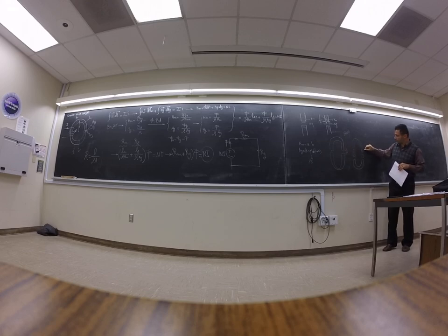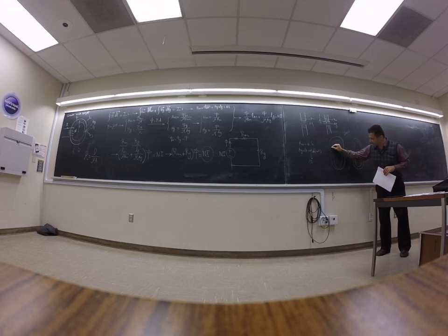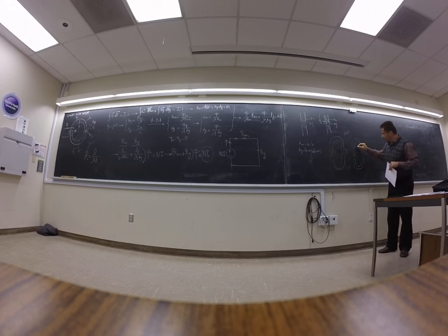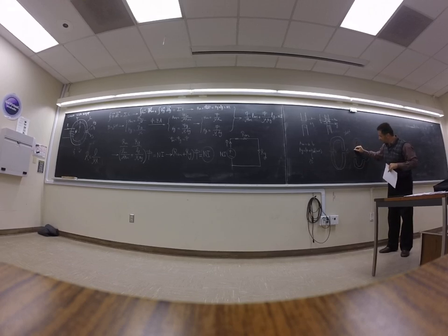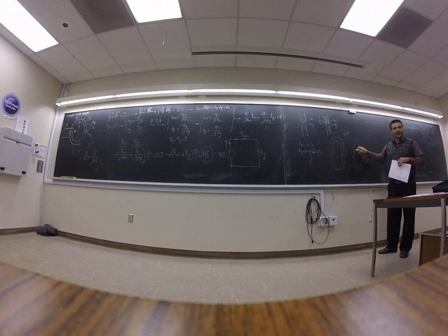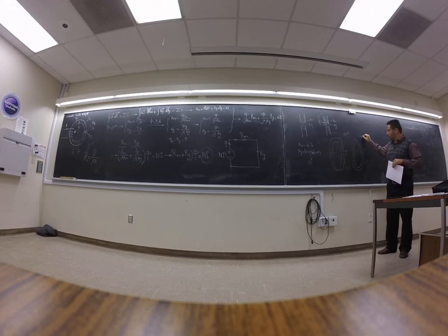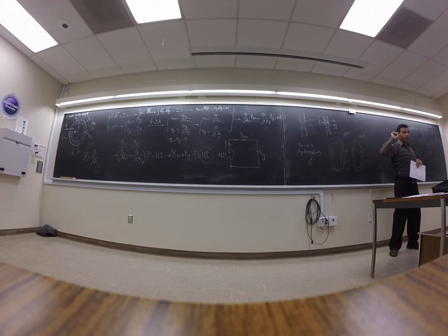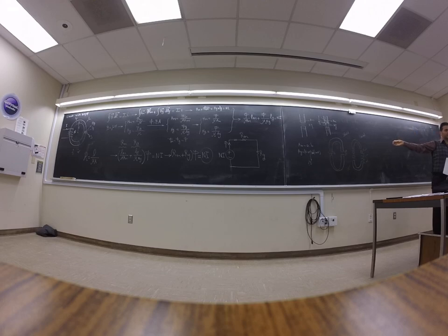They came up with 1, 1, and 1. They call it a distributed gap. They distributed the gap. So if you look at here, the flux is going to go like this because it's a big gap. If you look at here, the flux still goes, but there's a little bit of fringing. The loss dropped to 161, 101. See, 101 is about 40% of the loss gone.